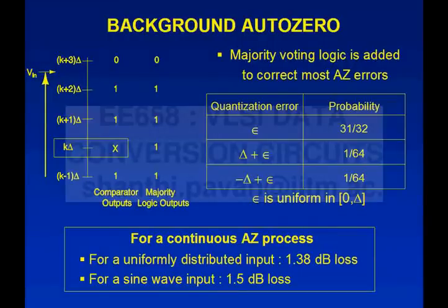This is what we do. The motivation behind this is what I just told you, right? So let's say the input was here. These are the comparator numbers and their references. If the input is here, then if all the comparators were competent and able, the outputs would be a thermometer code: all ones and then a 0, and all zeros following this, and then everything would be nice.